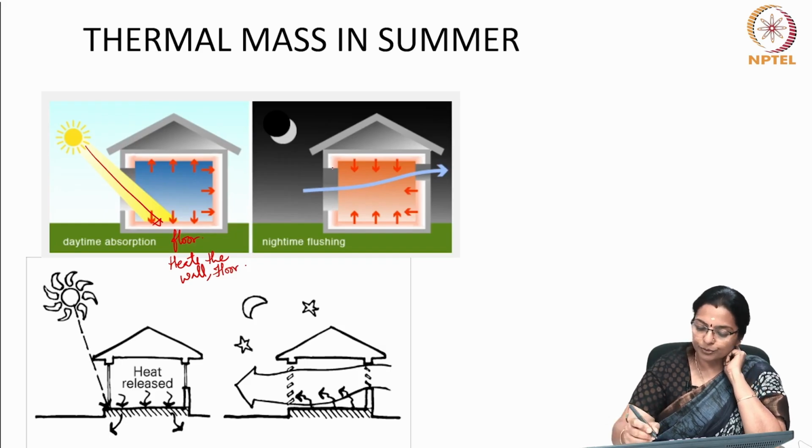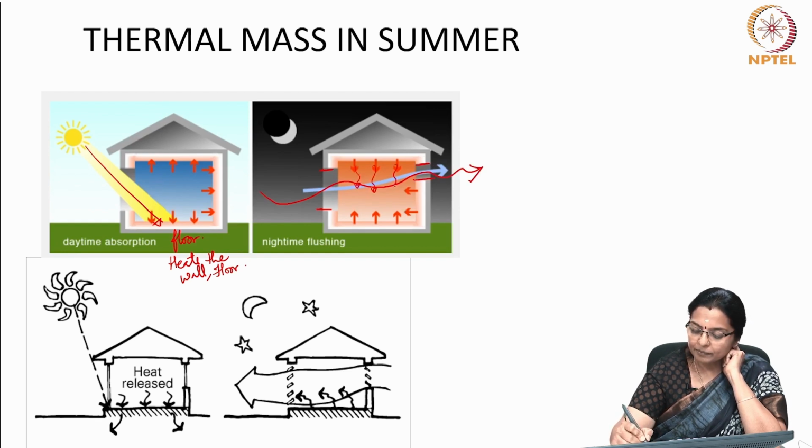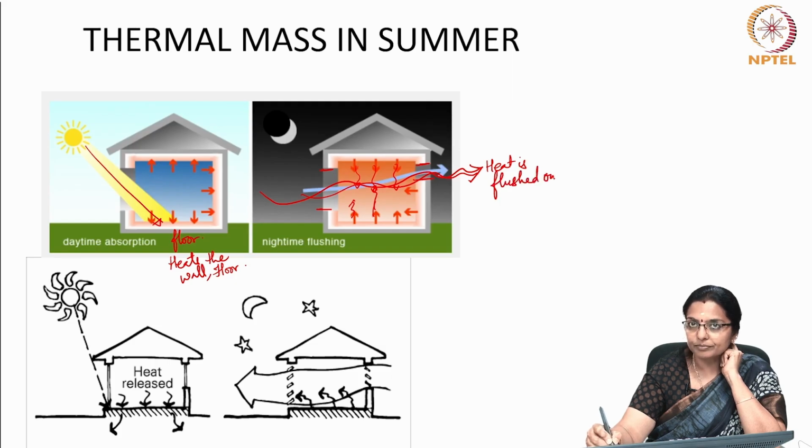At night, you keep the windows open, do not close them. Allow the breeze to flow, and whatever heat is released back by the envelope gets flushed out.